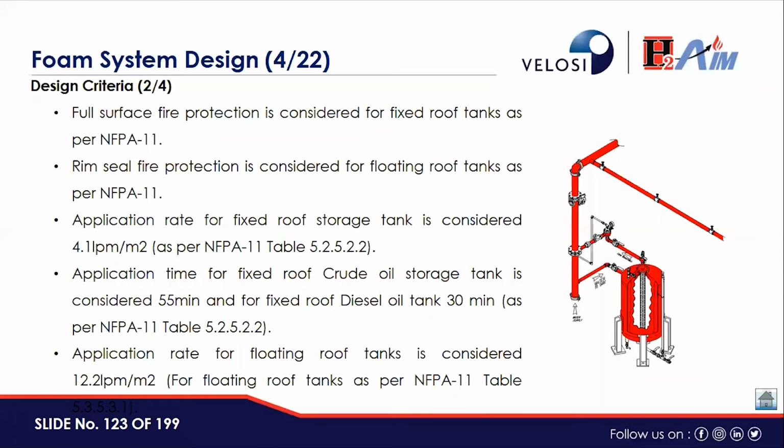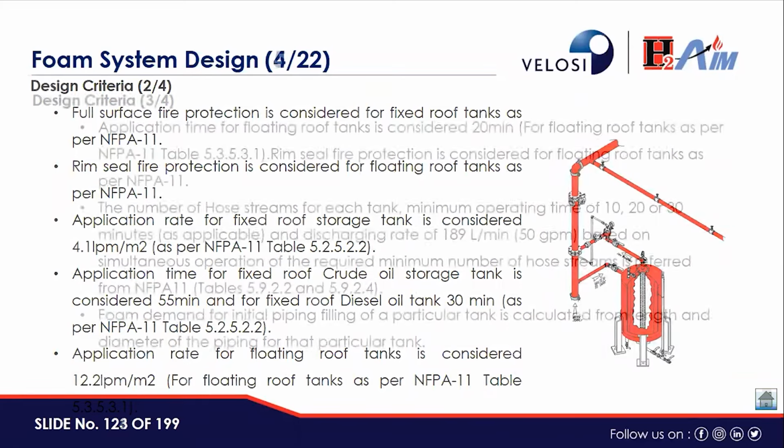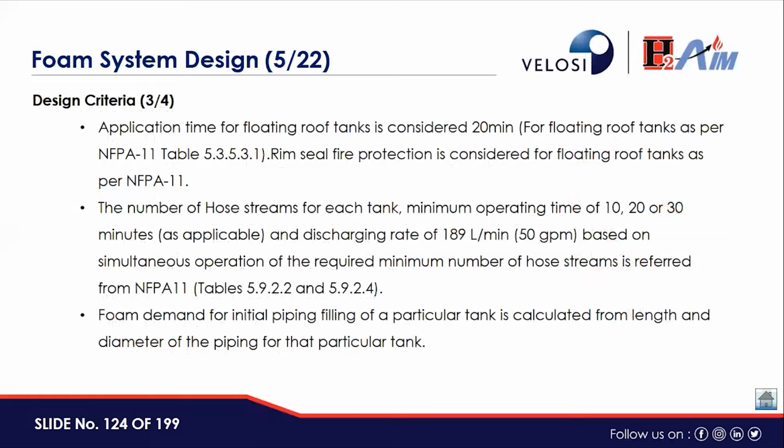Reference is NFPA 11 table 5.2.5.2.2. Application rate for floating roof tank is considered as 12.2 as per NFPA 11. Application time for floating roof tanks is considered as 20 minutes as per NFPA 11.